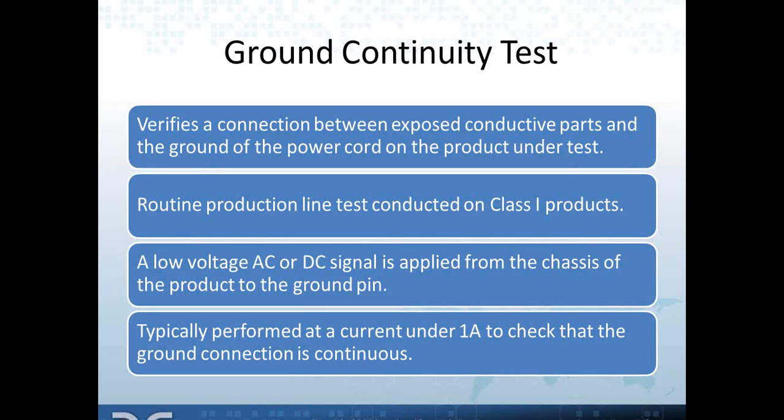Because these practices are so common, products with 3-pronged line cords are still required to pass a dielectric voltage withstand test, just like ungrounded class 2 products, but the integrity of the ground circuit is what protects the operator if a fault should occur in the insulation of a class 1 product.